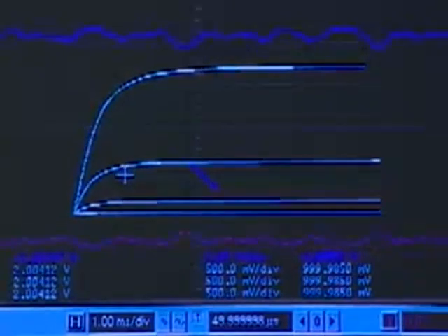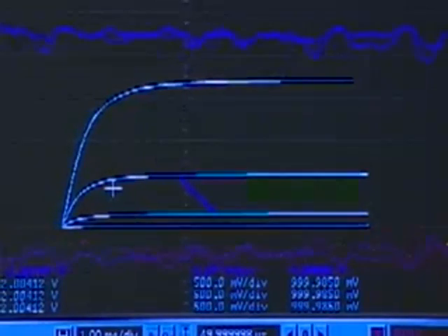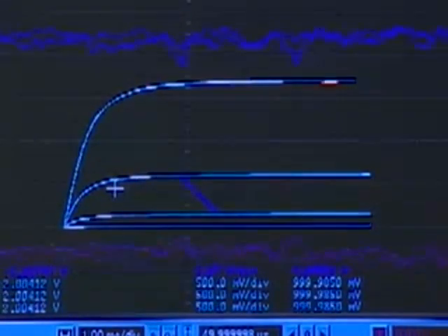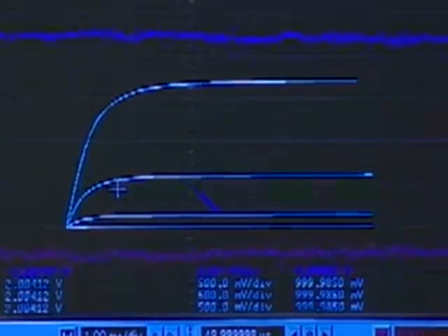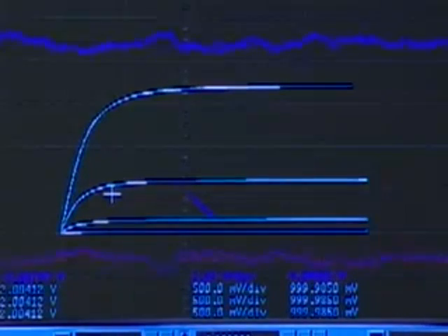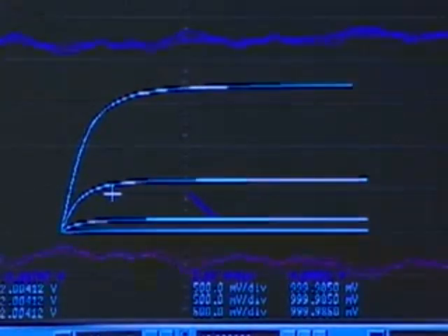So notice that as I went up here, the volume kept increasing. The volume kept increasing because the gain kept increasing. But as I got into the triode region, I began to lose my gain because, remember, the amplifier doesn't have gain in the triode region, when the MOSFET's in its triode region. And we also get a bunch of distortion out there.